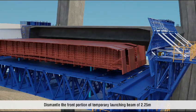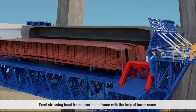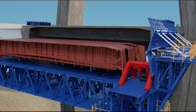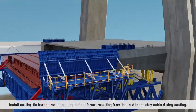Dismantle the front portion of temporary launching beam of 2.25 meters with the help of tower crane to avoid conflict with first stay cable. Remove temporary launching rail with the help of tower crane to avoid conflict with stressing head frame. Erect stressing head frame over main frame with the help of tower crane. Install casting tie back to resist